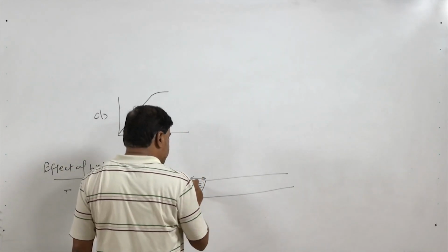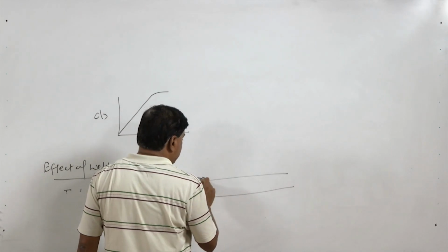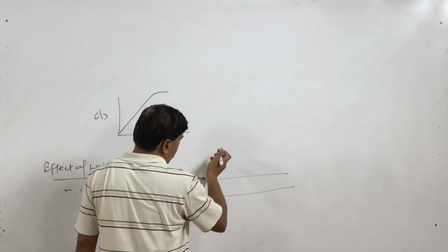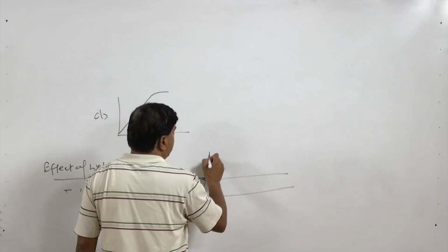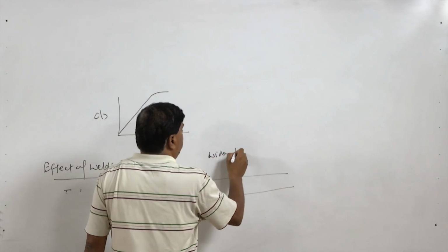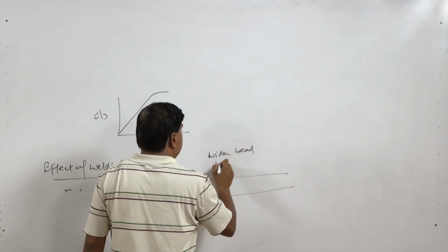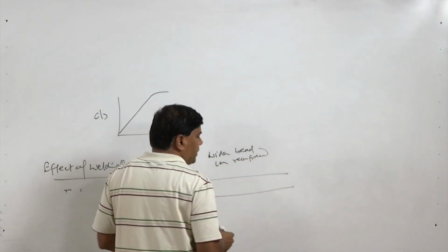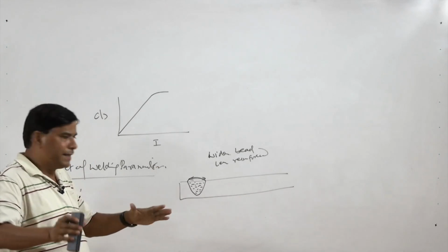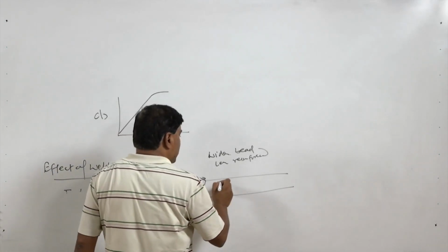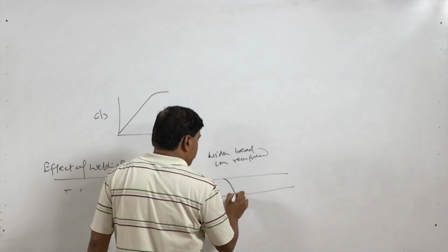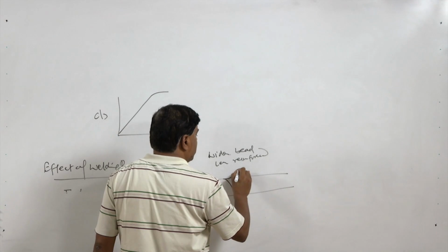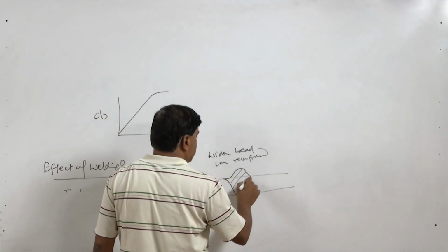But as this will be making a wider bead with less reinforcement, meaning the height of the bead is not much because molten metal starts flowing sidewise. On the other hand, for an optimum speed we will see that penetration is full and width is also limited and the distribution of the bead is also good.